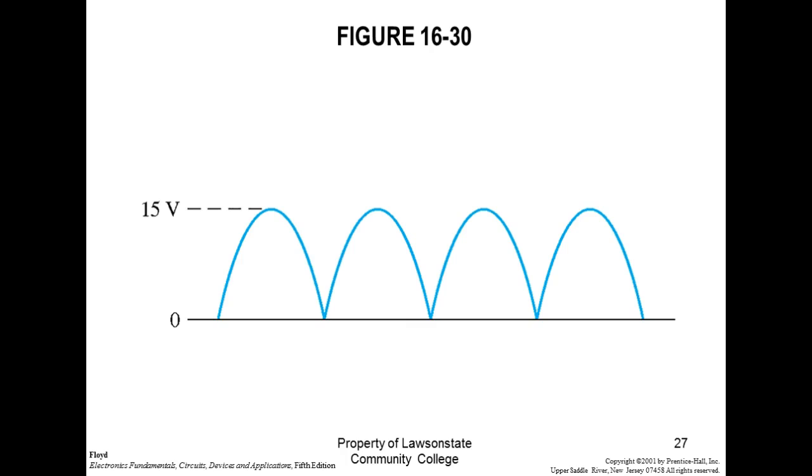So here, if this is 15 volts peak, then what would be the output? Remember, what we're dealing with here is DC, and DC is an average. So if it's got a 15 volt peak, you can't say we're going to get 15 volts out. We're going to get the average of this, not the peak of this. So this is an average. Y'all understand that? Yes or no?